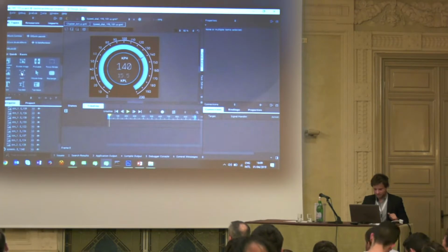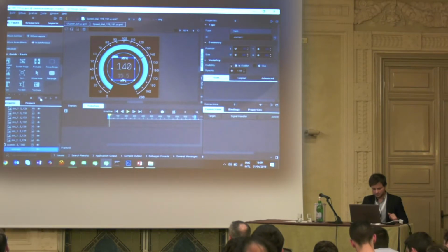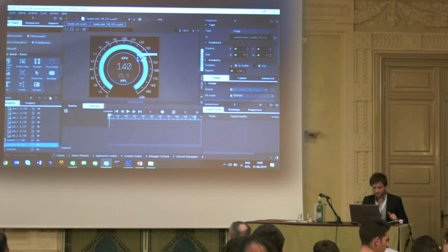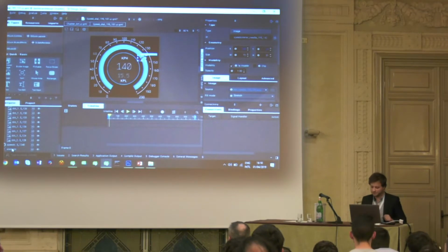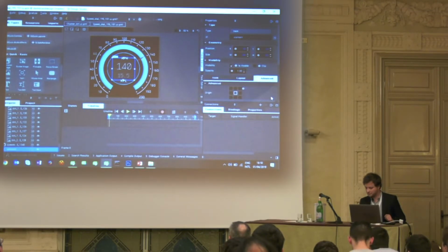And I'm going to add an item in the center of my screen. And I'm going to put the needle as a child of this empty dummy item, so that now I can just simply rotate the empty object, and that's how I get the rotation of my needle in relation to the center of this component. So as I said, I position my frame at the first one. I'm going to start recording keyframes, and I'm going to select my element here, and I will change the rotation.